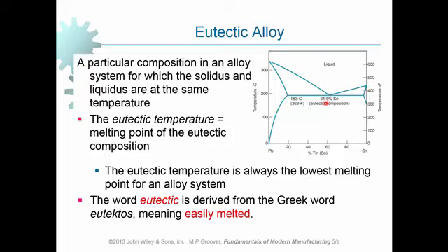And this is referred to as the liquidus point, the eutectic point, and this composition is referred to as the eutectic composition, right? Okay, why is it called easily melted? If we want to melt this material, for this certain composition, that is 61.9, you heat it up all the way. What you have got down here, this is solidus, of course. Below solidus, you can have only solid.